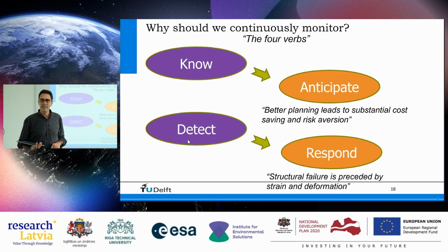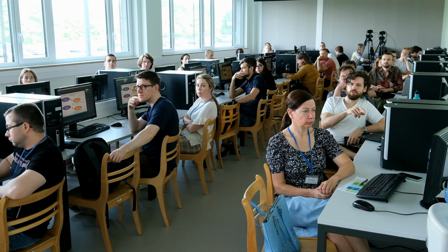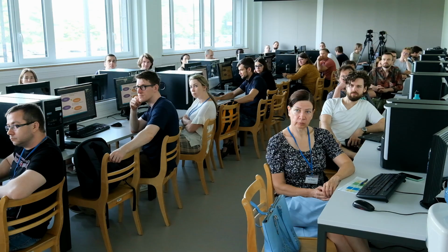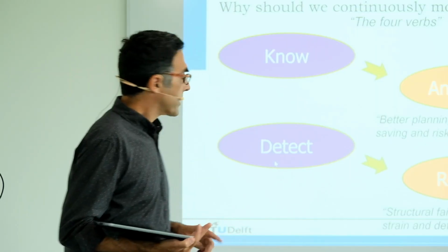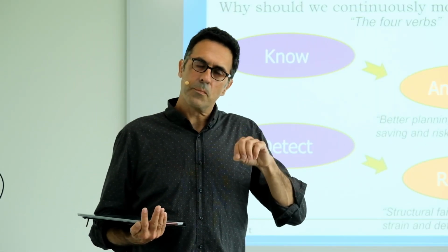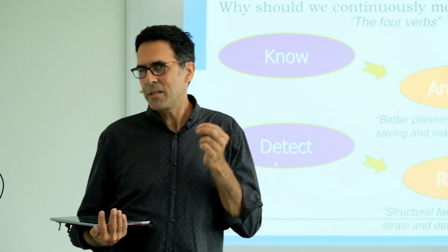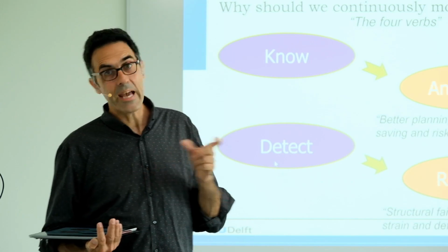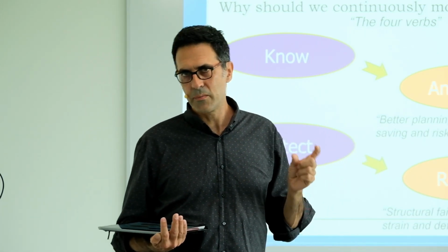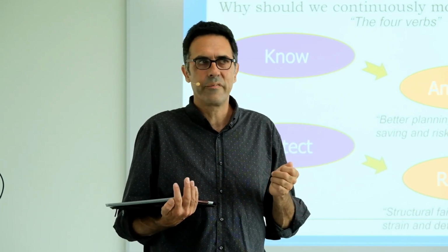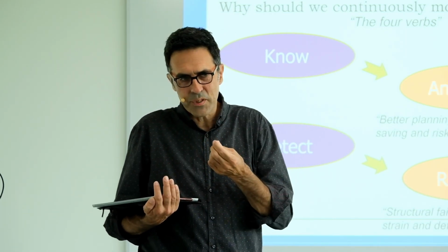Yes? In the map, I can see some dots next to the bridges, but not on the bridges. Are those meant to be for the bridges themselves? Yeah, very good observation. Indeed, like I said, the positions of the points that we put on the map with InSAR are not always that perfect. The best thing we can do is with X-band satellites, for example the German TerraSAR-X data set or the Italian COSMO-SkyMed data set. There we have basically the best positioning precision.